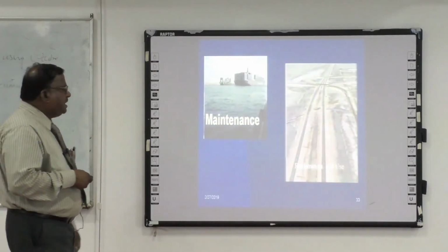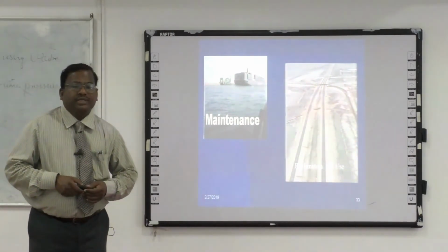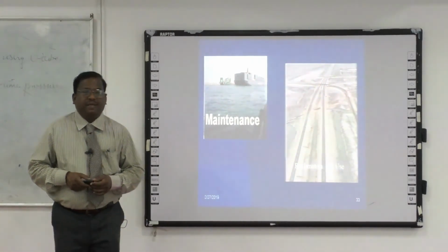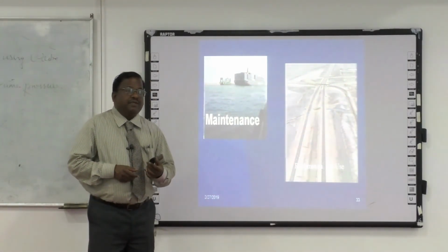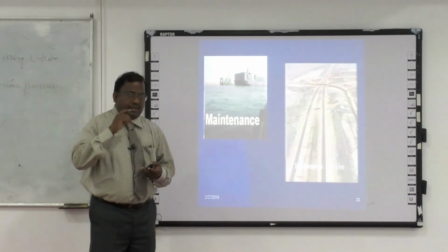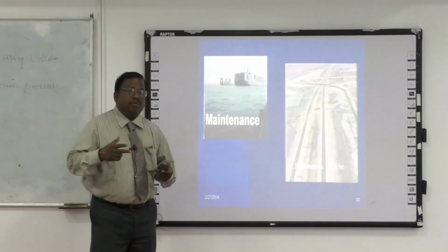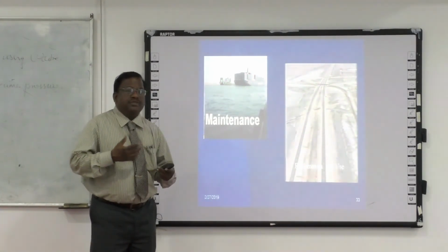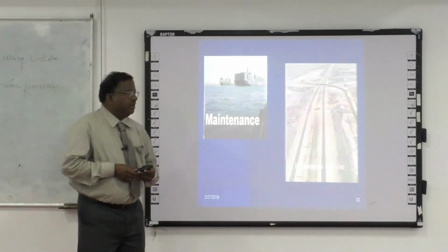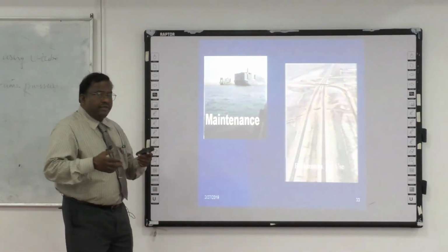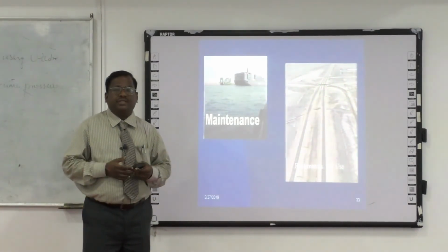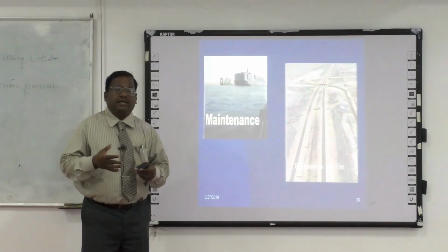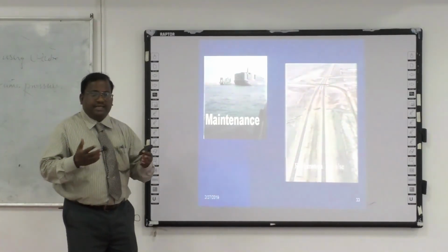Next is maintenance dredging. As we all know, once the port is developed, maintenance dredging plays a major role, because the depth of the harbor region as well as the navigation channel is to be maintained at a particular depth, so that vessels can move freely and the port operates most efficiently. Because of the monsoon and various ocean phenomena, underwater currents and storm surges, sediment deposition and accretion will occur at various locations inside and outside the harbor.